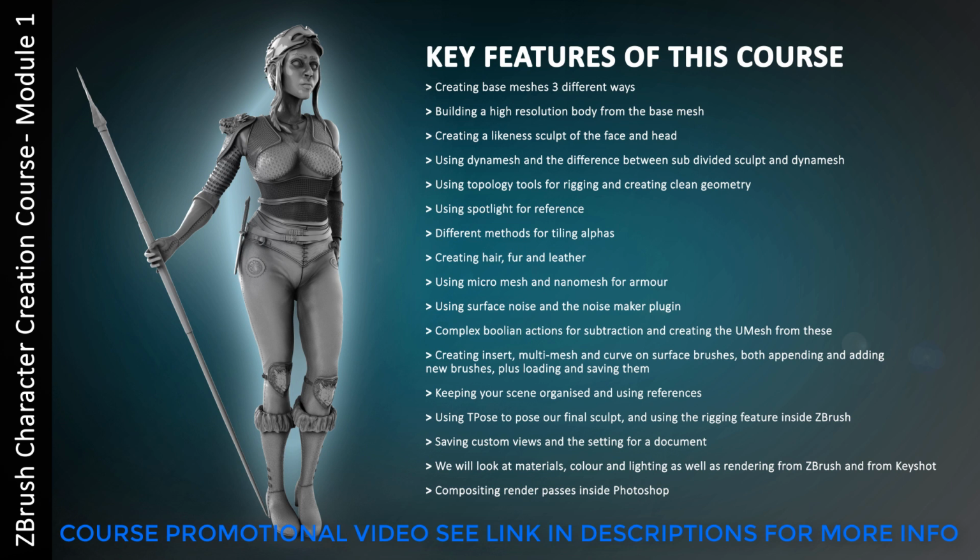We'll be creating hair, fur and leather using the sculpting brushes inside of ZBrush. We'll also be looking at using micromesh and nanomesh for armor, and being able to easily swap the micro meshes and nano meshes out to quickly give you a different effect. We'll be using the surface noise and the Noisemaker plugin, creating complex Boolean actions for subtraction and creating the UV mesh from these.